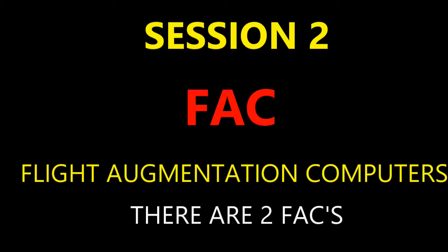All right. You do have an auto mode and a manual mode. Okay, so in auto mode, the FAC is going to compute the Dutch roll damping, because the whole idea is to reduce that threat of a Dutch roll. And so in auto mode, it's going to start computing that. It computes that damping and the engine failure compensation as well in the TOGA.